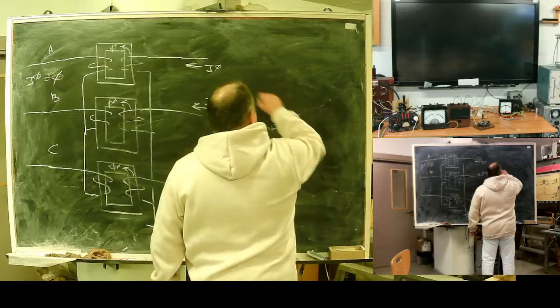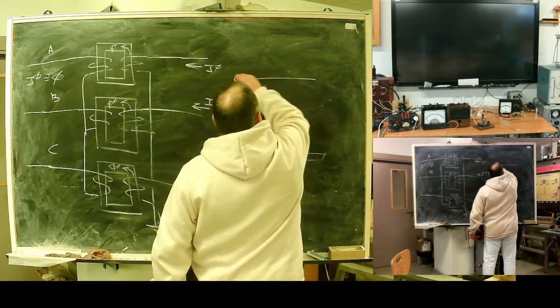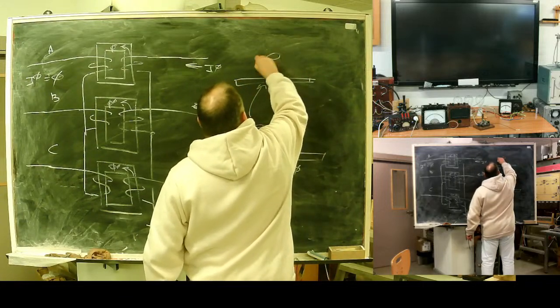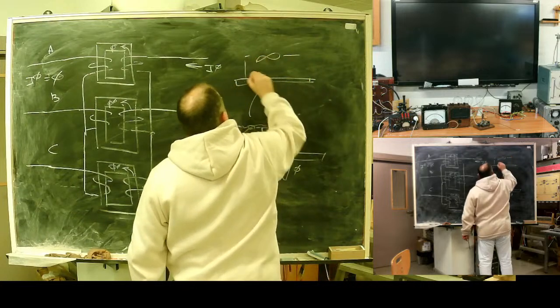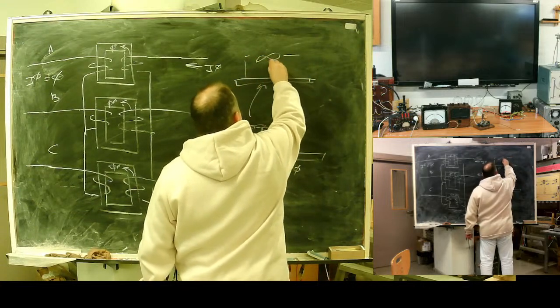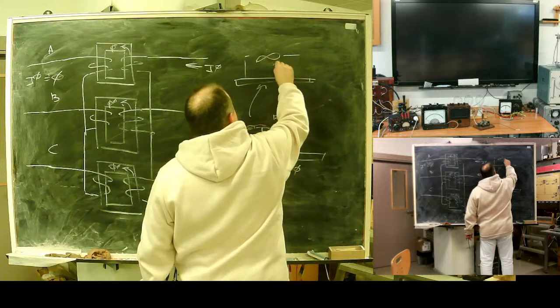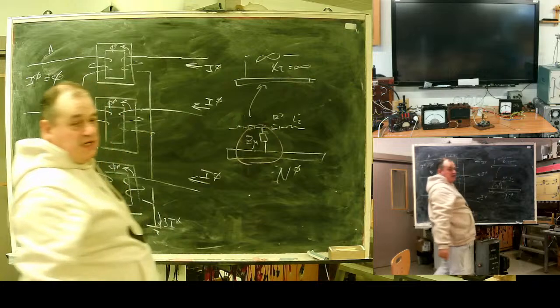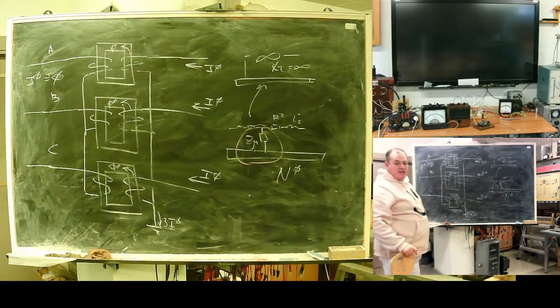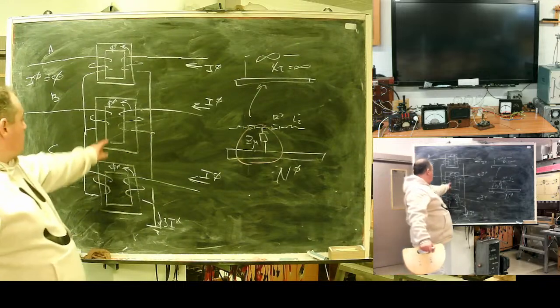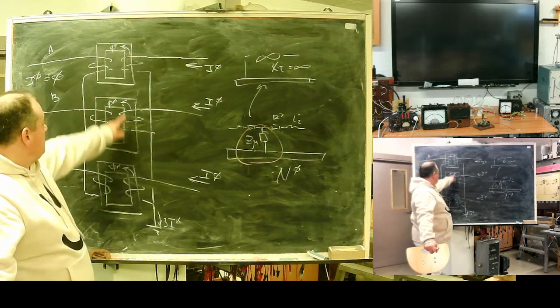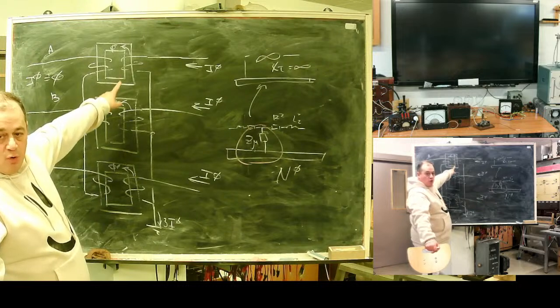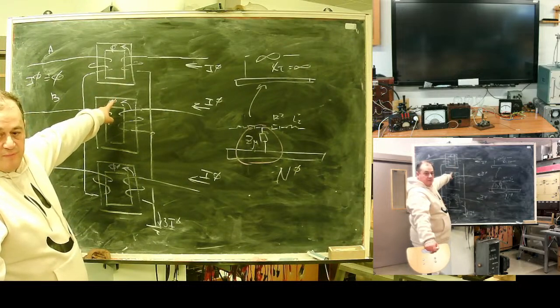So you can simply assume that in zero sequence the transformer reactance is infinite and there will be no zero sequence current, because here we have a free closed magnetic loop.